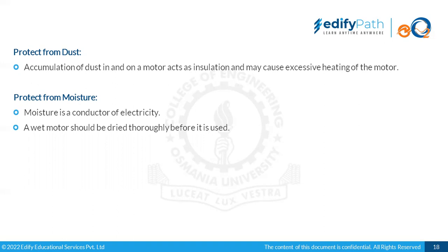Protect from moisture. Moisture is a conductor of electricity. A wet motor should be dried thoroughly before it is used. So from time to time, with timely maintenance, we should be checking for the moisture. Okay, because if moisture accumulation occurs in the starter, or in the case of motors,